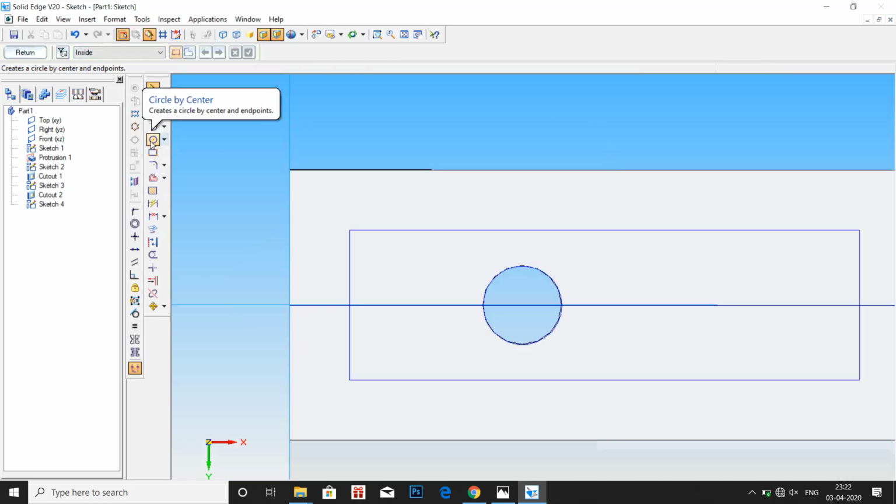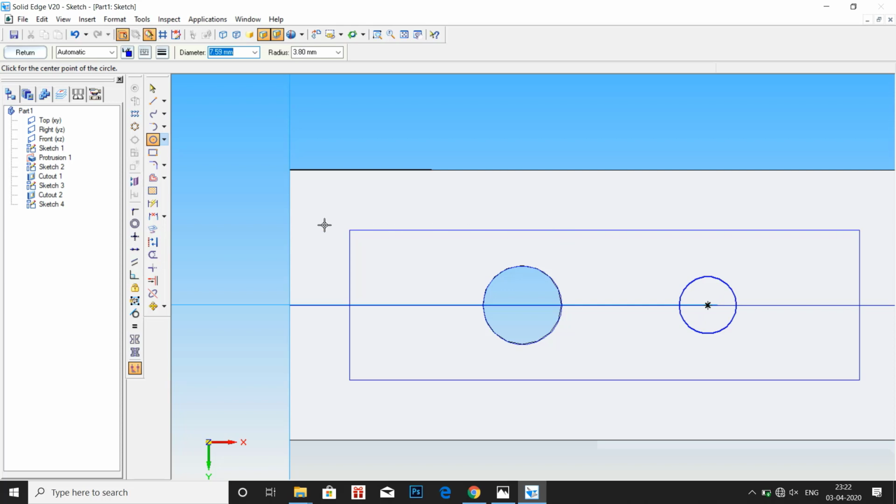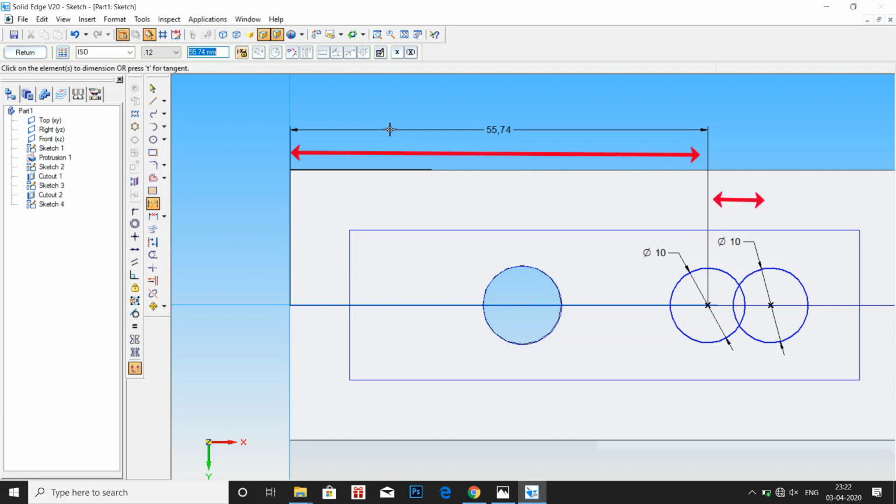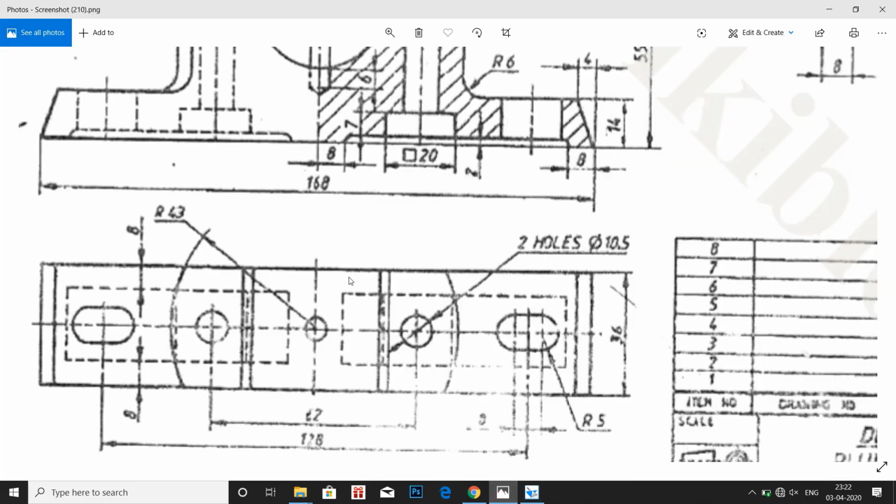Since from center to center it is 64 mm, and on the other side from the center you have 4 mm on either side, that is 8 mm. So 64 minus 4, we will have the distance from the edge of the center line to the center axis of the body equal to 60 mm. Let me show that. From here to here it should be 60 mm, that is 64 minus 4 mm. 4 mm is from half of the 8 mm center line.